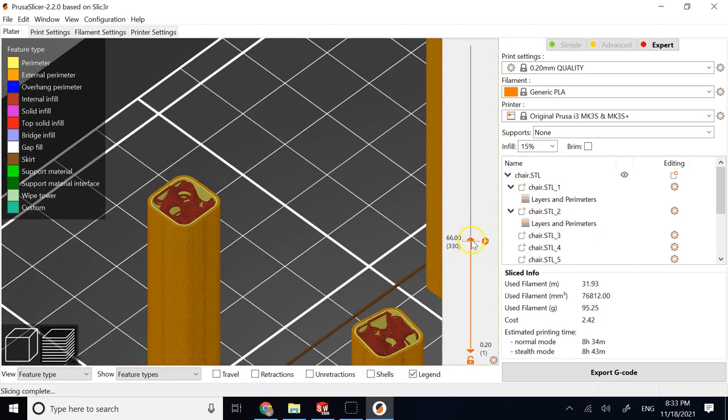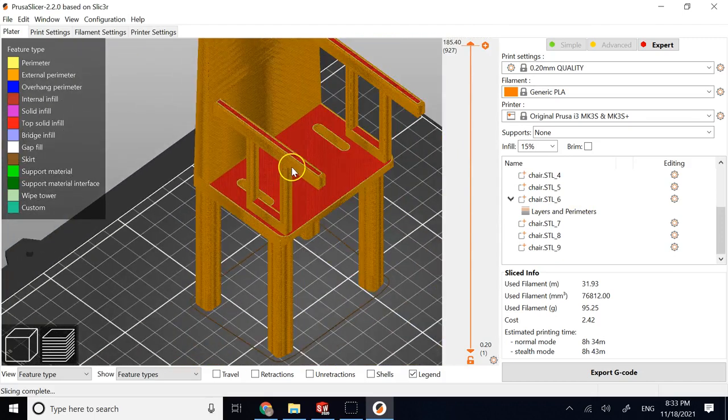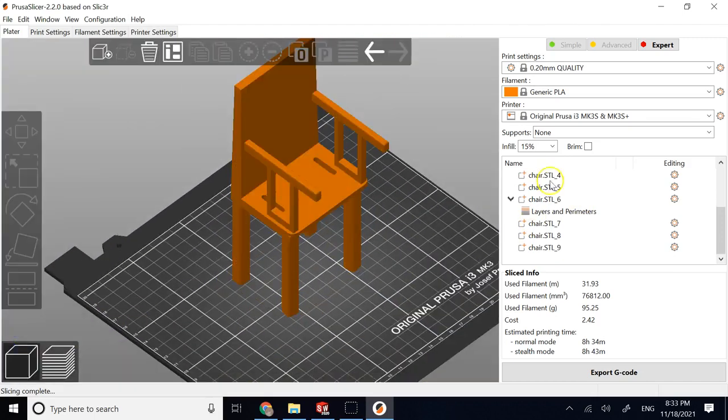Now, again, if it was different colors, if you have different spools, you had the software updated for multi-material, then not only you could change the number of layers or infills of each component, each part separately, you could also tell the software to print each one of them out of a separate spool, out of a separate color. And then you get your multi-color parts, really.